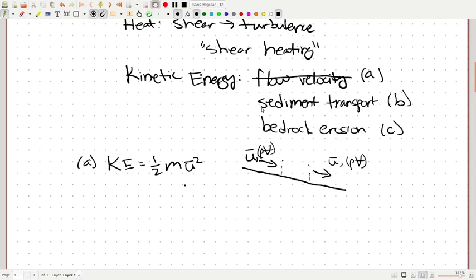There could be some sediment transport, but likewise, if there is a constant slope and a constant velocity, then shear stress is the same everywhere. And because sediment transport is proportional typically to basal shear stress, maybe to some power, then the sediment QS in and QS out are going to be the same as well. So we just have QS, QS. And so it's not very likely that sediment transport either.